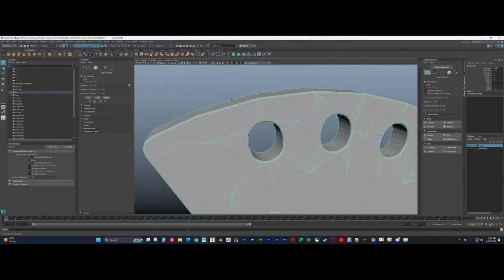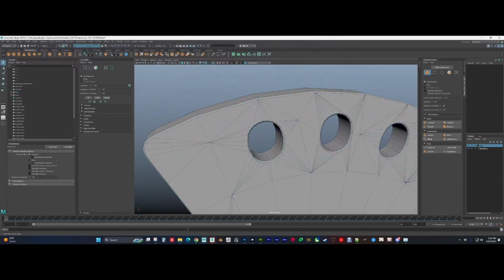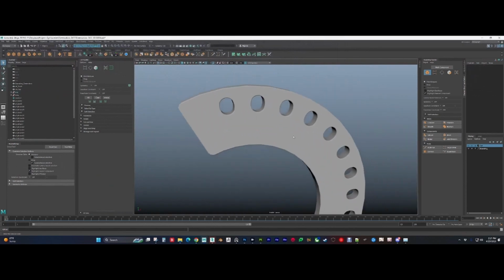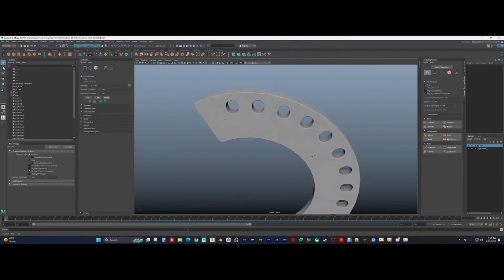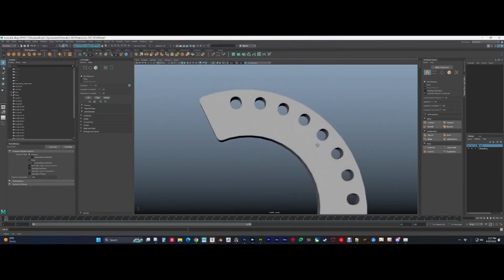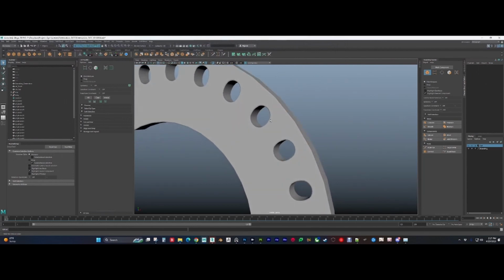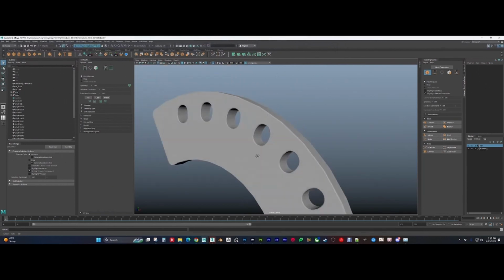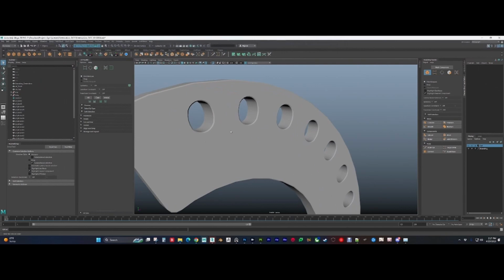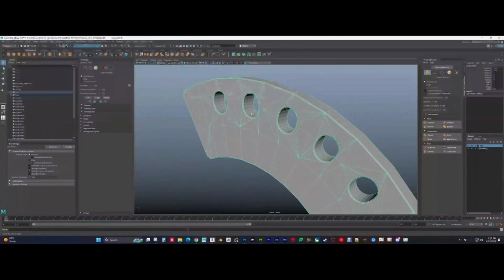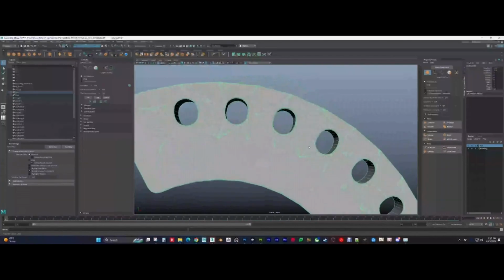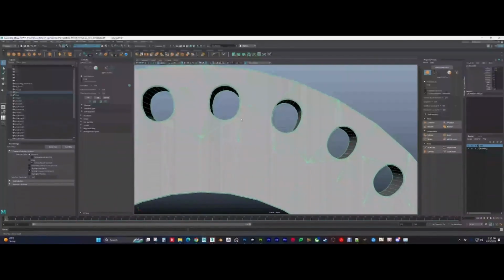It looks messy, but it works. So if I were to turn off edge faces and rotate around this, it looks clean. You can't see any kind of warping or bending on the actual surface itself, and that's mostly due to this being a planar surface. It's going to be different depending on if you're on a curved surface or not. But for this, I made just a whole bunch of terminating edges that terminate at a certain point, so they don't need to go beyond that point.